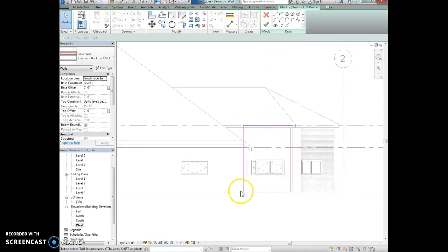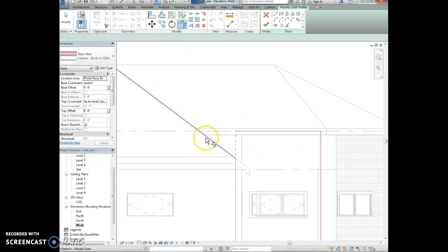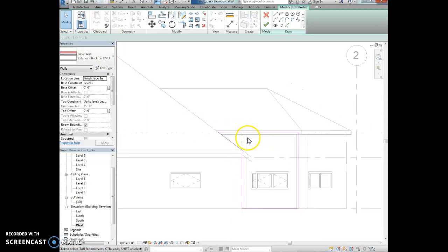And then that boundary line comes up again. We're going to use the Pick Lines tool, and we're going to select the edge of the roof. And we're going to use the Trim tool to eliminate the overlapping edges. So we want to keep this and that, and not that. We select what we want to keep. There we go. We need to make a closed boundary, so we're just going to put those two together. So now our boundary line is closed.